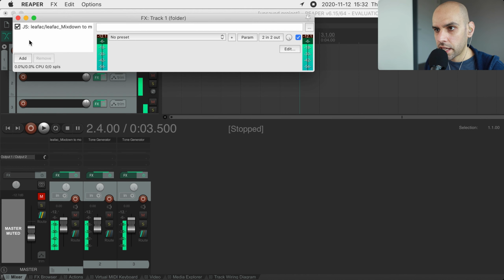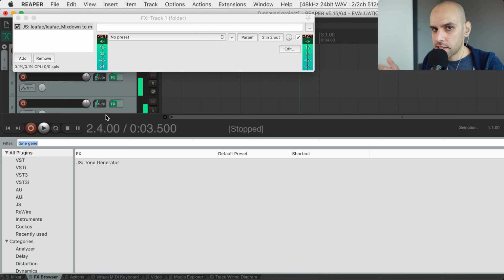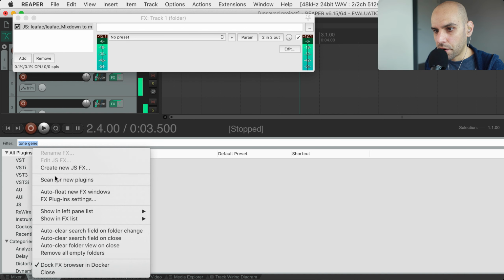Now let's do another one that is just stereo, and it's a utility. You can see that these are utilities because they don't even have sliders. You're just putting them on the channel and fixing something and moving on. So this next one will be taking the left channel and copying to the right, because you only have signal that you care about on the left channel. And of course, you could generalize this to make it multi-channel, and then you could maybe have a slider to select the channel that you want. But I'll keep things simple and just replicate what I think exists in Adobe Audition and do this copy left to right and vice versa.